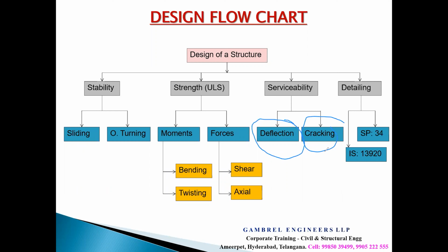Once everything is done, like the designing of a structure is completed, every piece of important information needs to be detailed in the form of structural drawings. These should also be as per the guidelines and details given in the SP34 code book. If it is a non-seismic zone structure, SP34 applies; if it is a seismic zone structure, we have to follow the IS 13920 code book. So SP34 and IS 13920 guidelines need to be followed when you are preparing structural drawings.